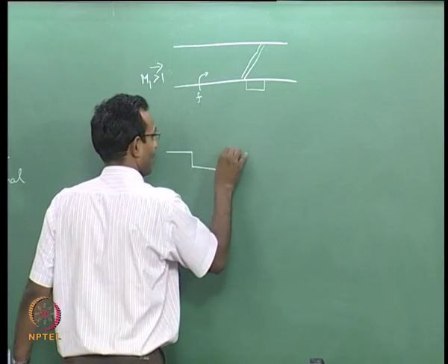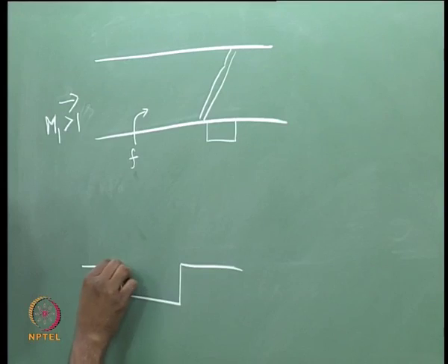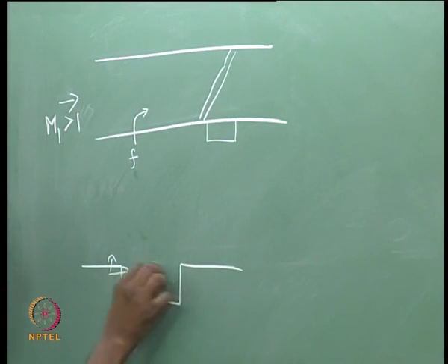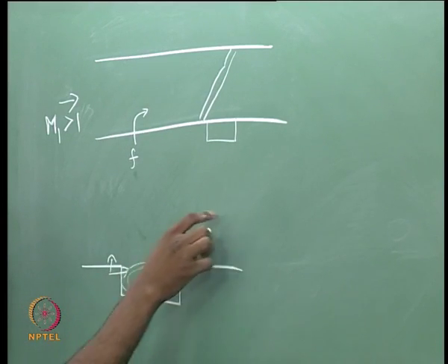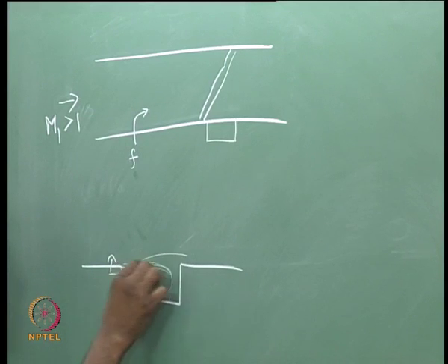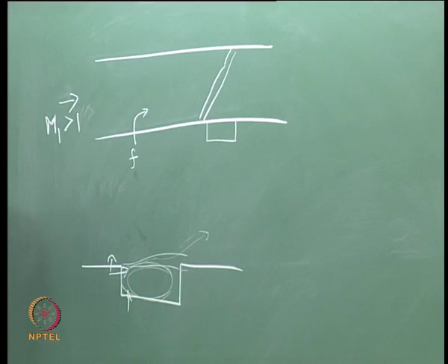People may have a cavity in the wall of the duct and inject it somewhere here or wherever, depending on each configuration, different Mach numbers, it can be any of these places they will inject, and this flow that is recirculating will mix that flow with this fuel and then take it out into this region. There will be a shear layer formed here which will be oscillating, which will send out fuel and air. This is one configuration.